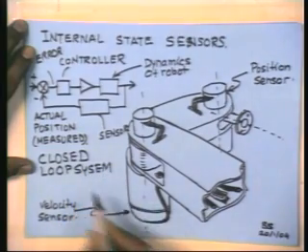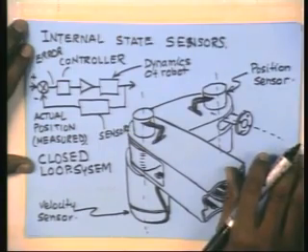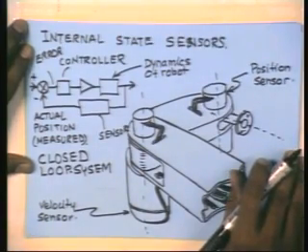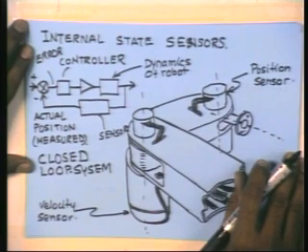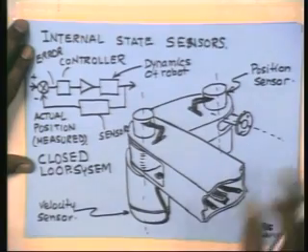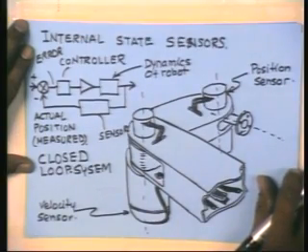A closed loop system has the advantage that if there are external forces which are disturbing the motion of the robot, which are always there, then it can make corrections and not depend on what the original command we have given for motion. As in the case of the stepper motor driven robot, if you don't have any feedback, then you can say go 100 steps, but 100 steps may actually be 98 steps because something obstructed it, but we have no way of knowing because we don't have sensors. So sensors are very, very important in making robots do useful and accurate motions.